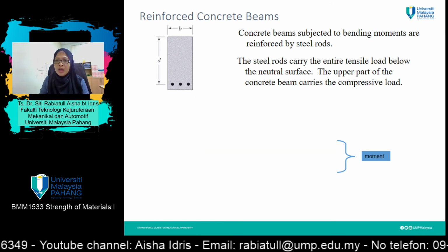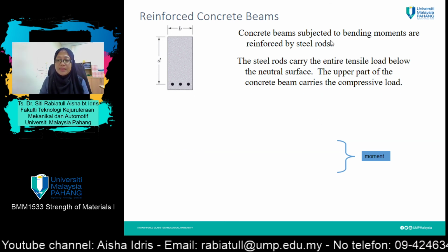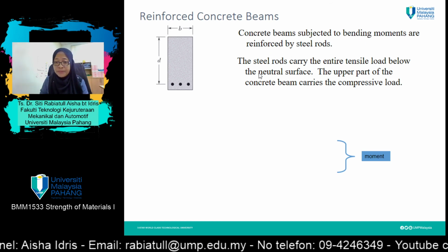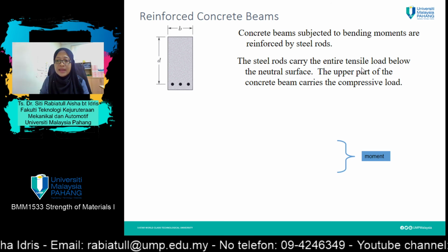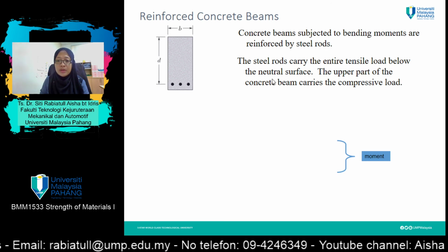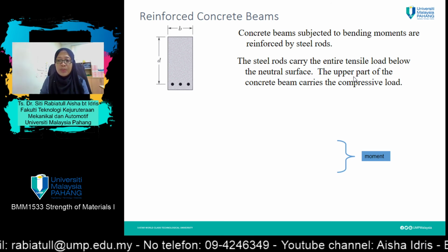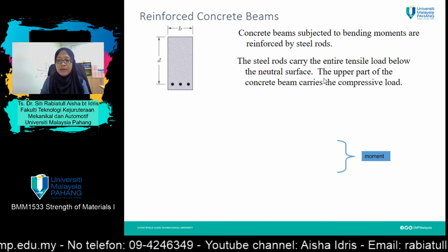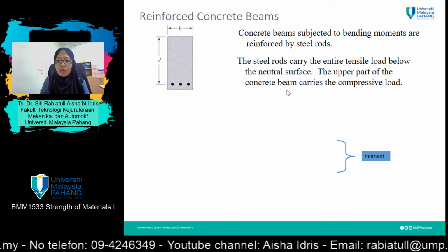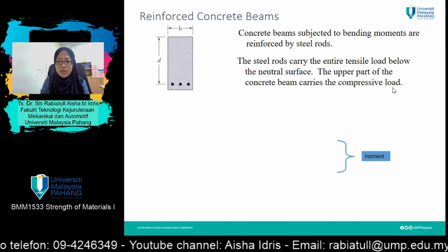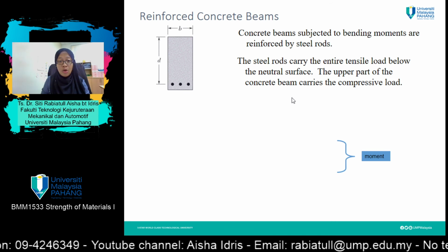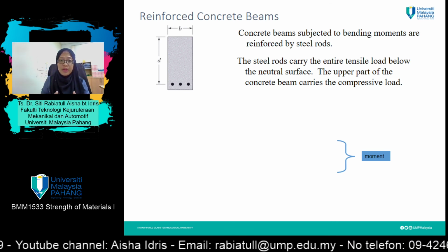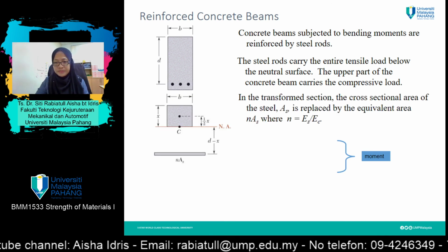Reinforced concrete beams subjected to bending moments are normally reinforced by steel rods. The steel rods carry the entire tensile load below the neutral surface. The upper part of the concrete beam carries the compressive load, because steel always resists the tension, and therefore the upper part of the beam will carry compressive load.